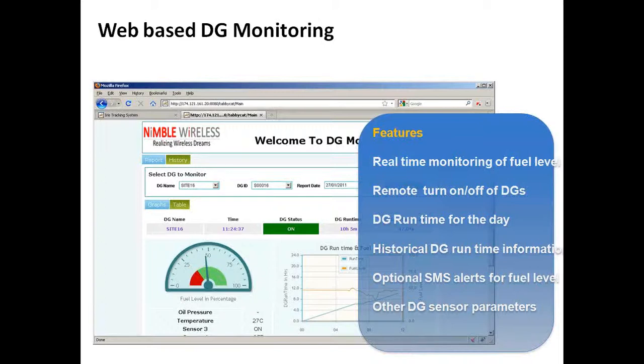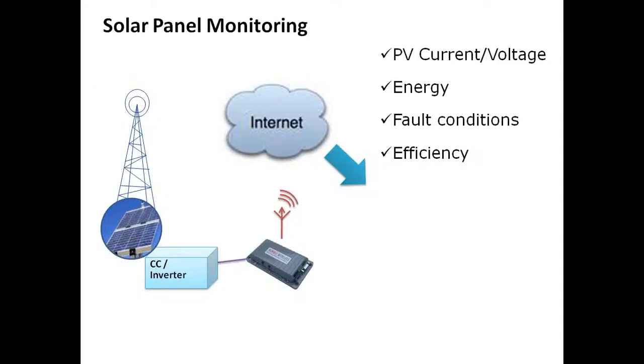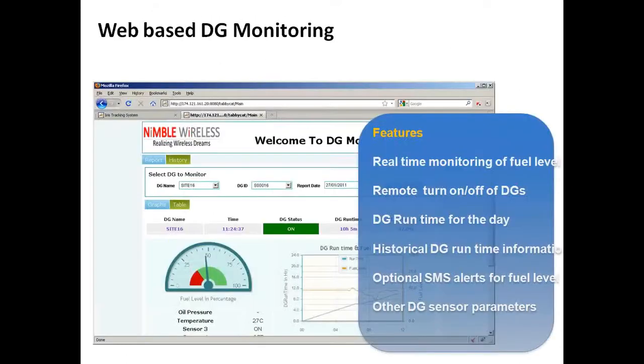The way to connect this monitoring device would potentially be connected to your DG set through some important signals, for example, DG on and off signal, or it could be connecting to the DG kilowatt hour measurement instrument, or it could be connected to the battery of the DG. In all these cases, it is trying to measure or trying to extract data from the DG, let's say in a periodic manner, once every 10 minutes or once every 15 minutes, and it transfers it back to the internet, to the server, and to the central monitoring station.